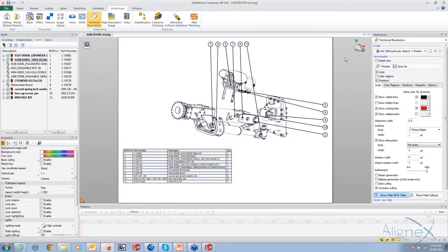So what happened here, when I added my knuckle kit, they were not in the correct order here. So I just went over to my BOM tab and I selected to sort by a specific column. So I could sort by part number, I could sort by BOM ID, description, and that's going to determine what's being chosen there. So by sorting at the top, just getting them in the correct order, that's what we're talking about. So I believe, Troy, is this what we're doing to answer your question? Yes, okay. There's another question here. Can you sort the BOM by a part number? Yes, I believe I just answered that as well. Jody, did that answer your question? Okay. All right, well, please continue to ask questions. There's all good information here.